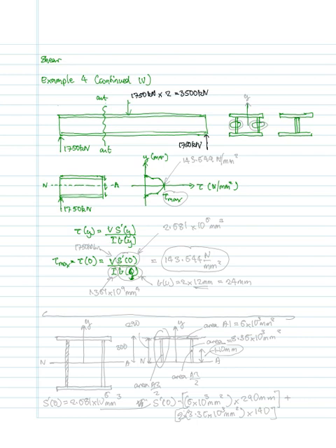Now going back to the cross section, hopefully you should realize that in terms of applying that equation, let's say that the two web members were moved to the center and they were actually touching each other, you should realize that the calculation shouldn't be affected by the position of these two web members relative to each other, because there's nothing in the formula that considers their distance apart.